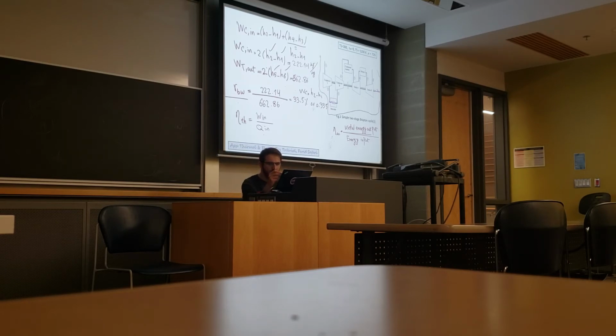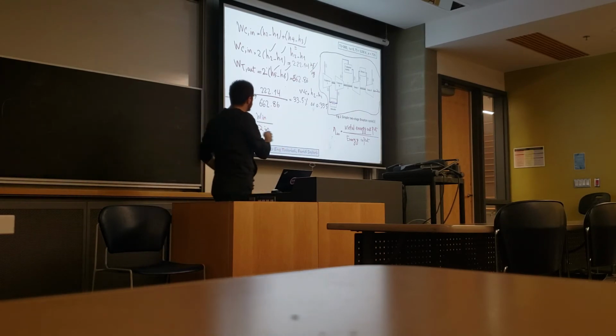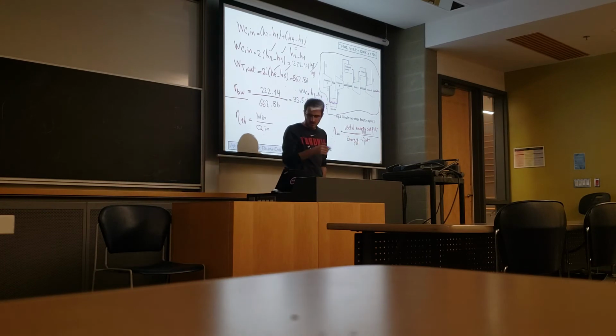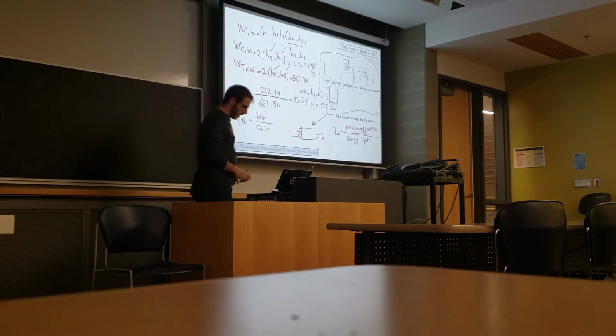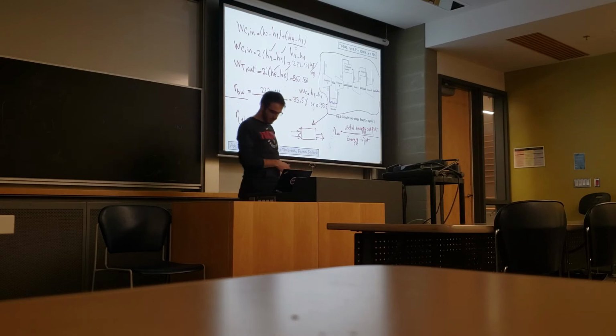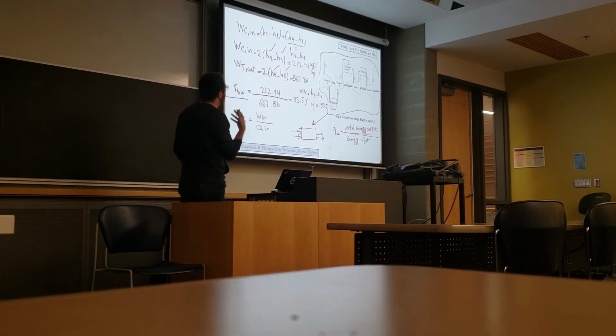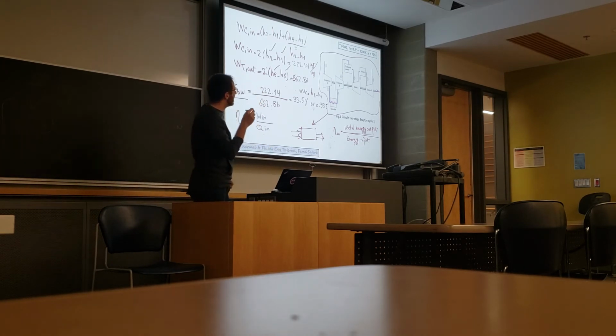So you draw a line around your whole system and you see what flows of energy are coming in and going out. So you make this big system, as I told you, like a box with inputs and outputs. And you consider just the useful outputs as the numerator and all the inputs, energy flow inputs, in the denominator. So here, what is the main purpose of this Brayton cycle? Is power generation, right?